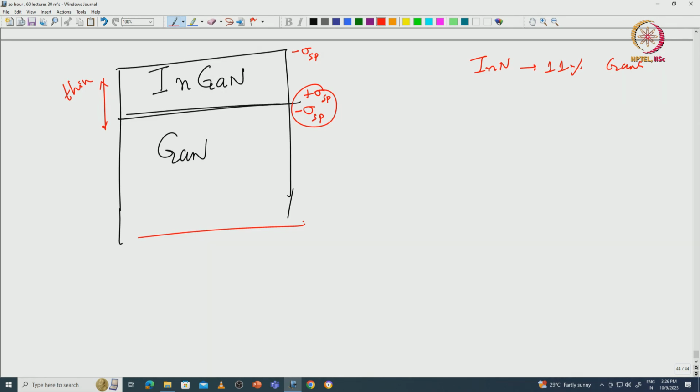So, there is a material growth restriction, and also a lattice mismatch restriction. If you have indium gallium nitride of, say, 20% indium and 80% gallium, the lattice mismatch with the gallium nitride below is so huge that this layer will relax. You do not want it to relax, but it will.